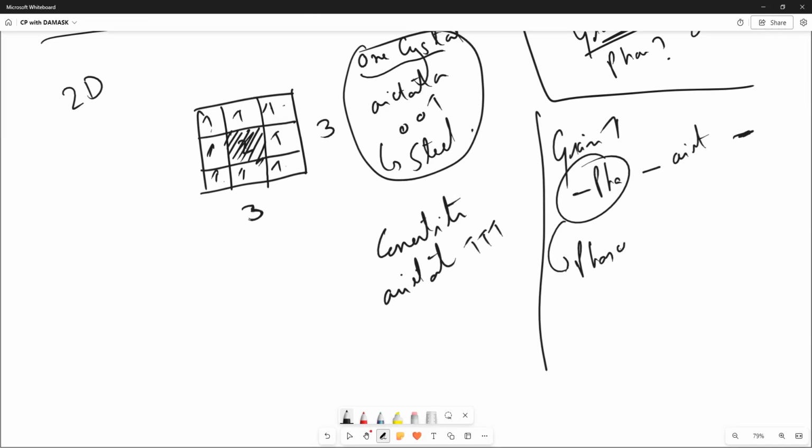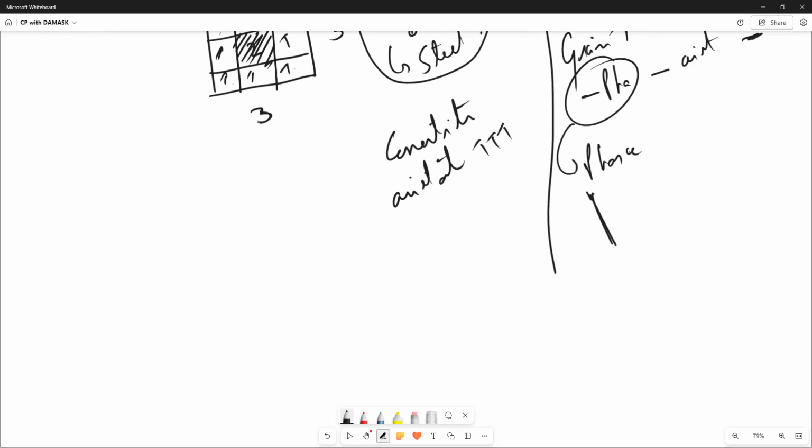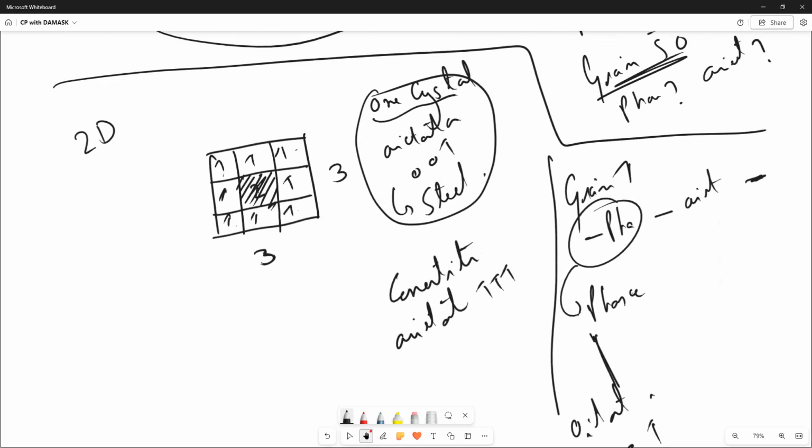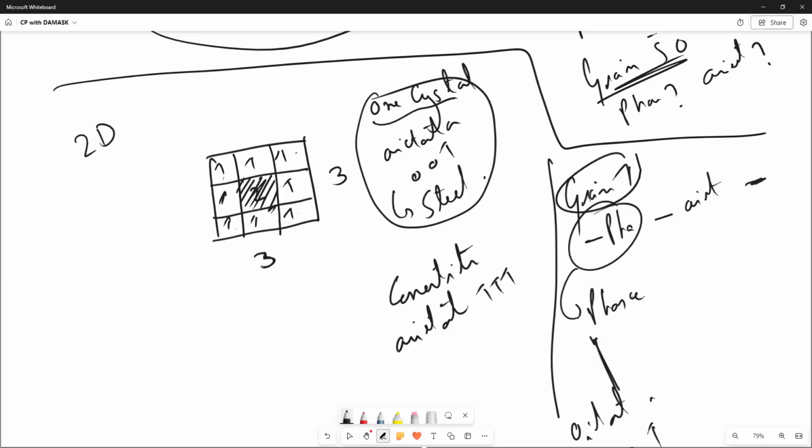I will write all the slip systems that can activate, what the resolved shear stress value is, what crystal orientation it has, what the hardening rule is. And then I will say it has orientation in terms of Euler angles, I will define it 001. And now this information will be used for all these points where I had written 1.